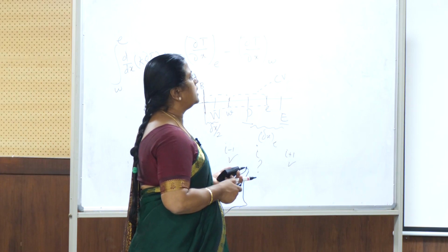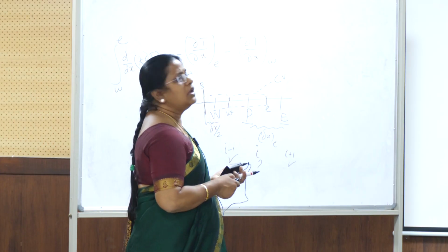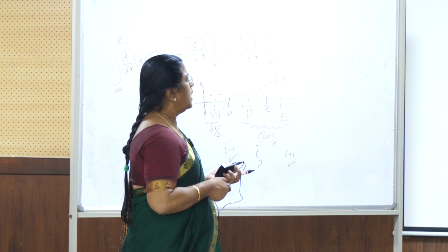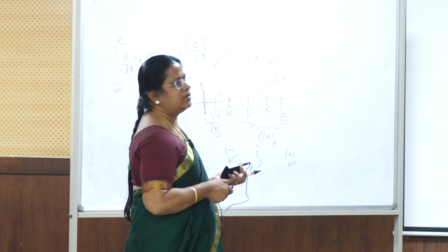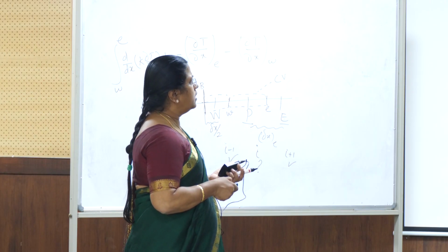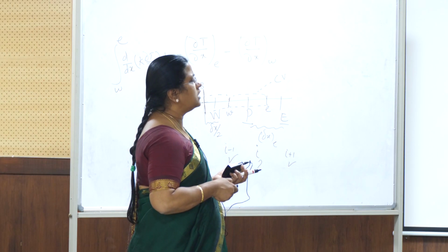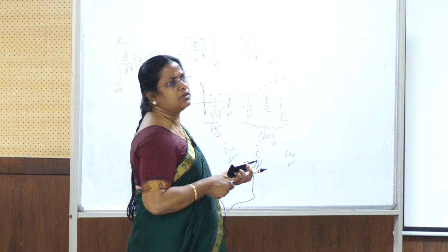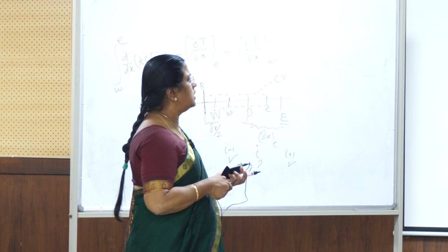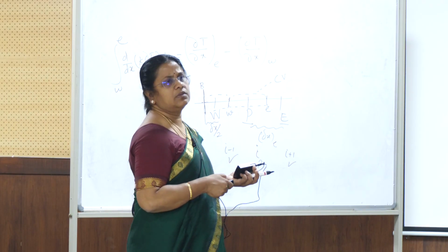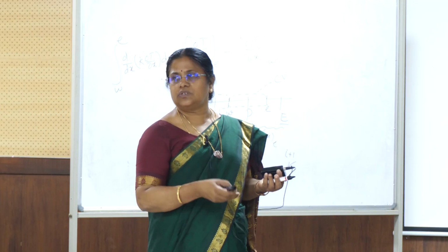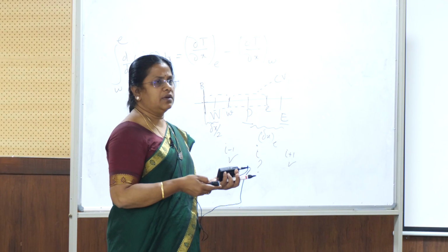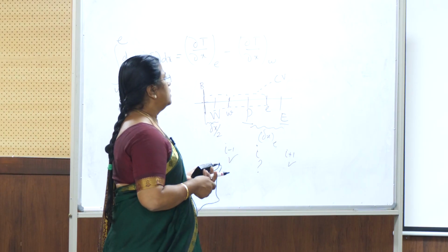Convergence criteria. Already we came across the convergence criteria. We are going to specify that. This is the equation and the residue we are writing here. How are we writing it? The value of this is nothing but our conserved variable, temperature, velocity, some variable value here minus the previous one. The difference between the previous iteration and the current iteration should converge to a certain limit, whatever we specify.